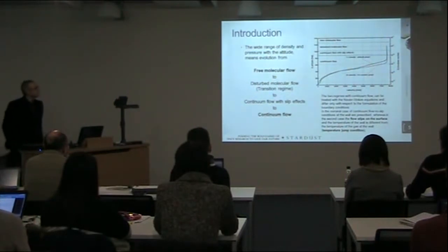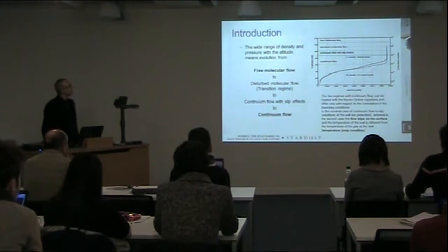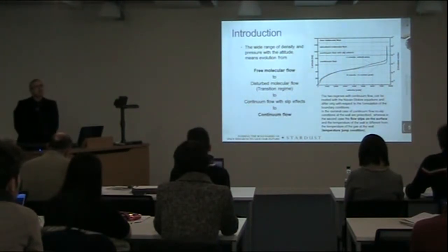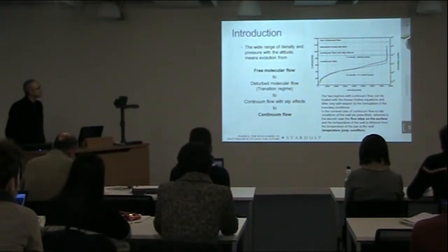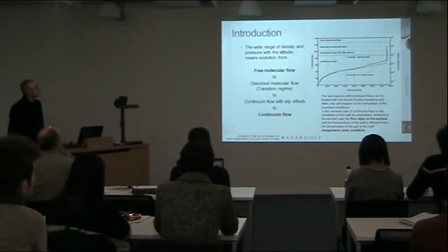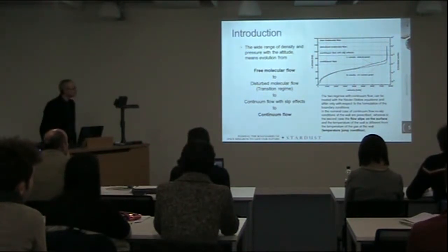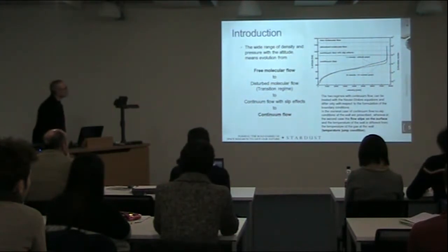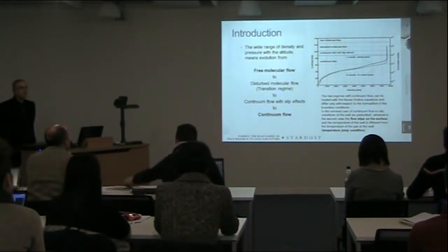Another thing that is peculiar to the entry flows is the fact that due to the change of characteristics of the atmosphere, we will actually have different regimes. We will start from the upper part of the atmosphere where we have free molecular flow. Then we go through a part which is called the transition regime. So it is still molecular but with higher density. Then we have the continuum part.